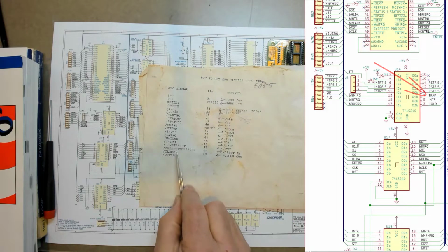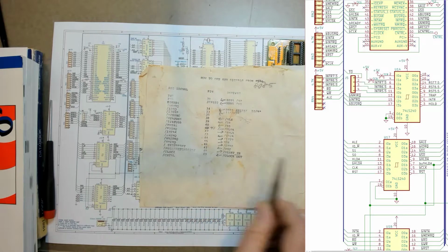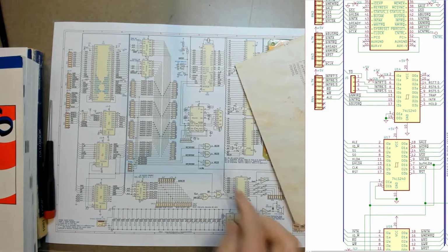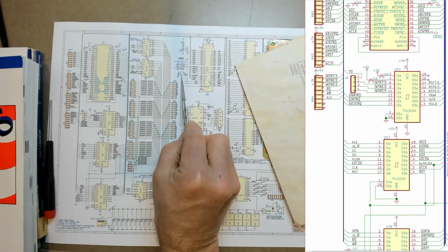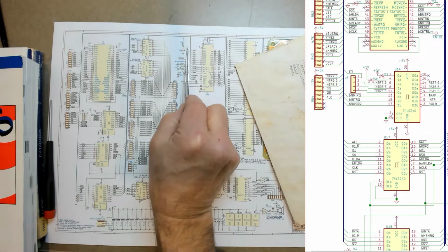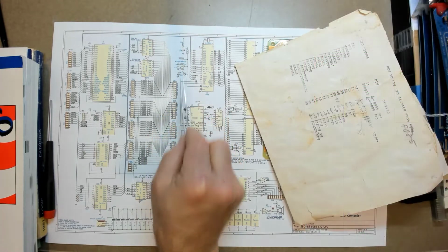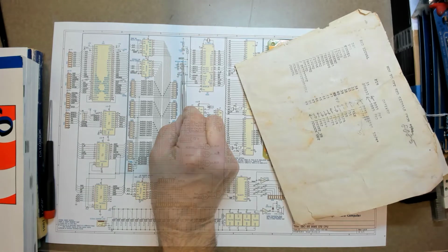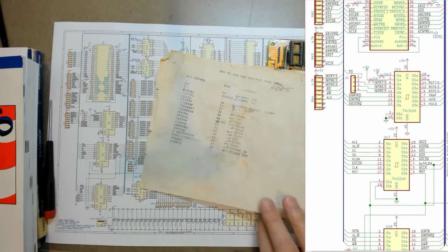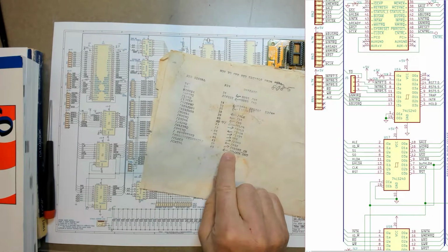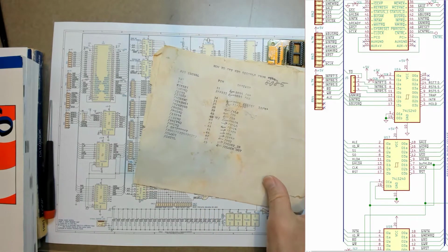Pin 48 is the push button reset, which goes to the reset in on the processor. It also is connected to the onboard pull down, the supervisory, and has this little RC that gradually pulls it up. So that's the push button reset. The last input is the system reset, and I'm going to talk about that a little bit more in a minute. Right now, let's go on to the output signals.